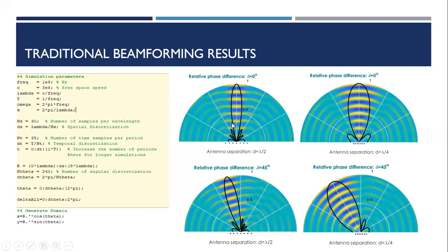So as you can see as well, with the main lobe being generated, there are side lobes as well, and depending upon the high power beam width or the antenna separation D or HPBW, we will have the number of side lobes decided by that. So this test case was repeated with different.